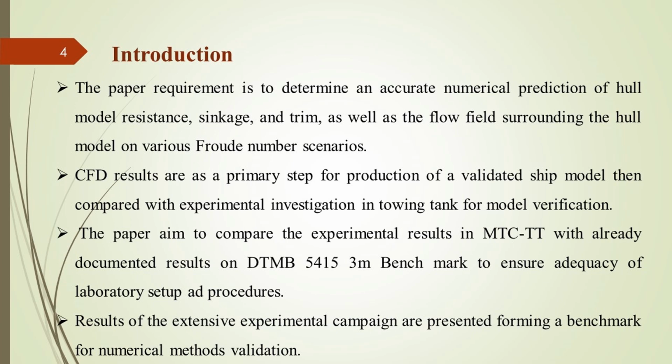This paper is used to determine an accurate numerical prediction of hull model resistance, sinkage, and trim, and the flow field surrounding the hull model at various Froude number scenarios. CFD results are a primary step in the production of a validated ship model, then compared with experimental investigation in the towing tank for model verification.